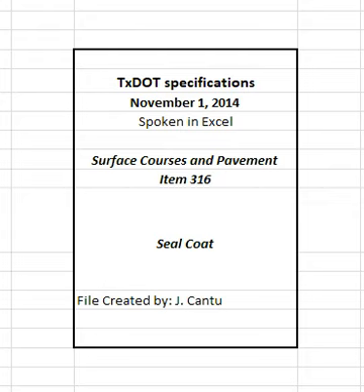3.1.3 Calibration. 3.1.3.1 Transverse distribution. Furnish a distributor test report, less than 1 year old, when tested in accordance with Tex-922-K, Part 3. The department reserves the right to witness the calibration testing. Notify the engineer 3 days before calibration testing. Include the following documentation on the test report. The serial number of the distributor. A method that identifies the actual nozzle set used in the test, and the fan width of the nozzle set at 12 inches. Bar height.